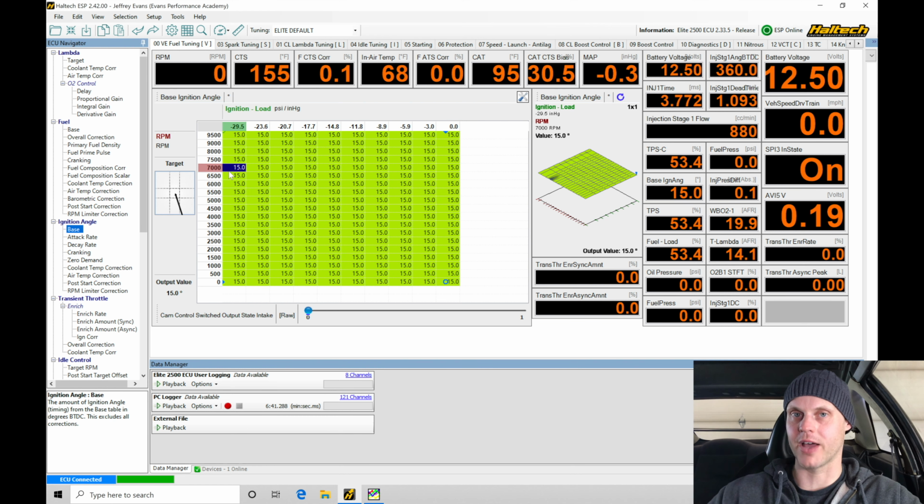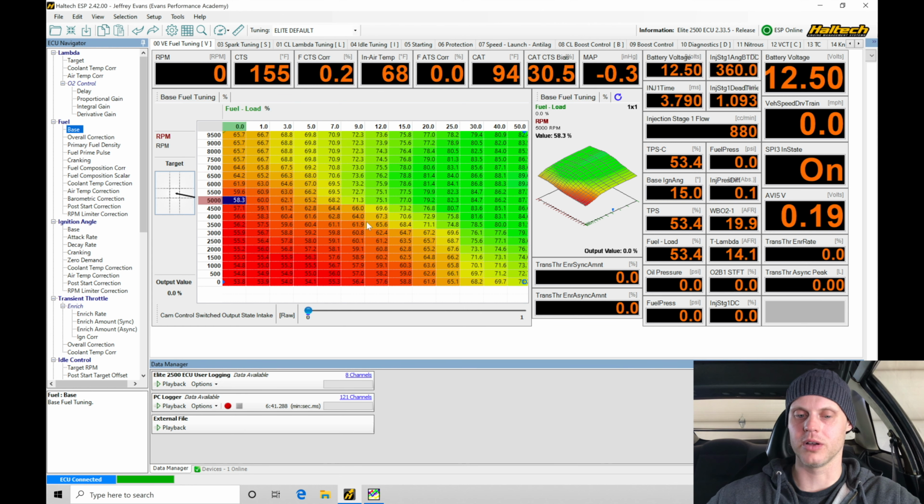We've started off with values at 15 degrees in our non-VTEC table here, so the 0 table. Again, we have 0 and 1 in the 0 table here, so that we don't have to worry about knock or pre-ignition occurring as we're calibrating our fuel. This is always what I suggest that you do. Start off with low spark timing values, tune out your base fuel table here, get that sorted out, making sure that your short term, because we're in closed loop, making sure that your short term trim is as close to